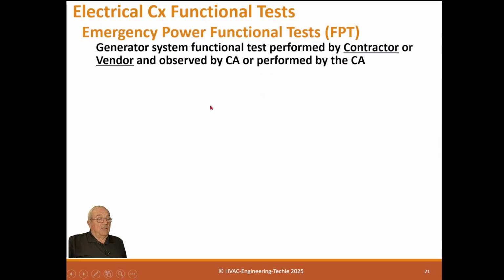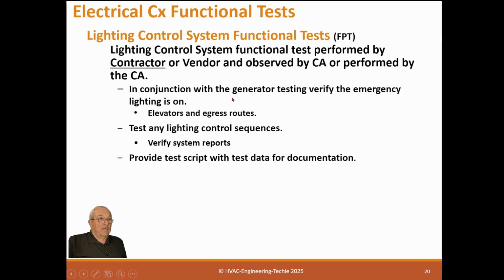Now, let me back up. The other thing on this test is to verify the motion sensors or vacancy sensors, either one. This becomes difficult if you have an office area with 30 occupancy sensors. Of course, the difference between occupancy and vacancy sensors is that an occupancy sensor detects when it's occupied, a vacancy sensor detects when it's not occupied. Sounds the same, but it's actually different.